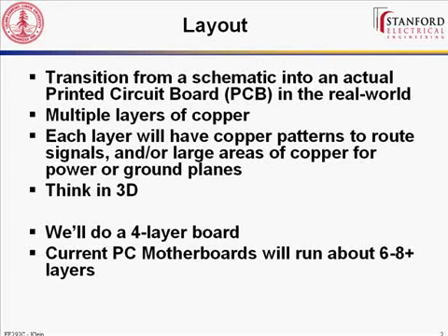Yeah? How does price grow with number of layers? All right, so how does price grow with number of layers? It depends on your manufacturer. Advanced Circuits, who our research group has used for a lot of our boards, has some specials online, and it's $33 per board for double-sided. No quantity restrictions if you're a student. So you can buy just a single board at $33. A 4-layer board is $66 from them. Now, if you get to a whole lot of layers, it will grow a little bit faster because it makes it a little bit harder to get your yield. But it's generally linear or slower.